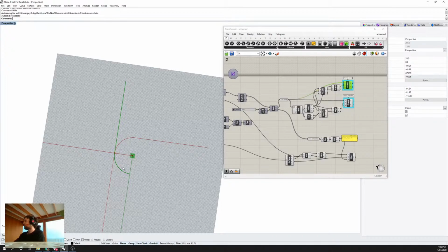So the one other thing that we need, well, there's a couple of other things we need to do if we really want to get this perfect. First of all, we don't want to orient this line segment, and second of all, we want to move our part in this negative x-axis by the length of the bend, and then we really will have a perfect representation of the bends before and after the part. So let's go ahead and have a crack at doing that as well.